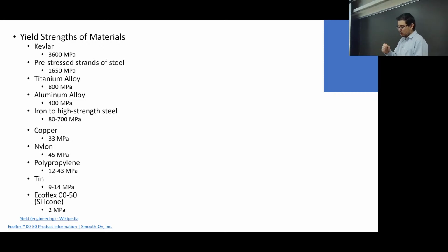So we actually got one of these bars. I don't think it might have been the actual one, I don't remember though. And we would do these hardness measurements. So often there's a very nice Vickers or Brinell hardness machine, and you have this little ball that comes down and you press in and you measure the size of the indentation. But they also make these portable machines that you can push a ball or some type of hard surface into the material, and then it measures how deep it goes, and that's going to give you an idea what the hardness of the material is.